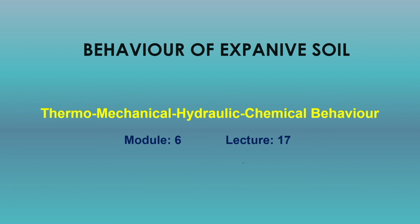In the previous class we learned about the different behavior of different types of clay such as montmorillonite, illite and kaolinite. We learned about the swelling, the shrinkage and the compaction characteristics of different minerals, and today we will be learning about the swelling, the hydraulic and the compressibility behavior of montmorillonite, illite and kaolinite.